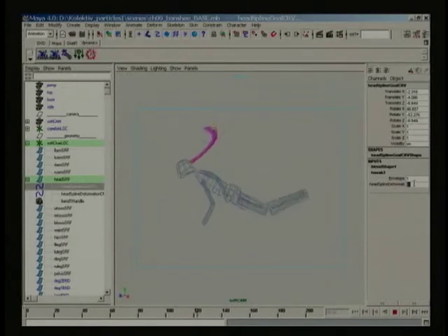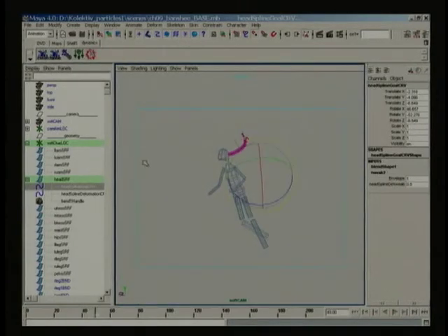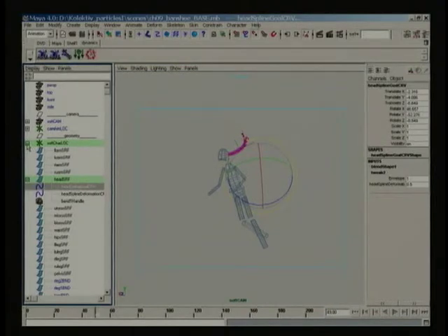Using a ramp to control the goal PP distribution along my curve proves to be a nice, quick way to control the weighting between points on my particle object. If I wanted these straps to stretch, however, I could have simply skipped creating the joints and created a wire deformer out of my deformation curve.